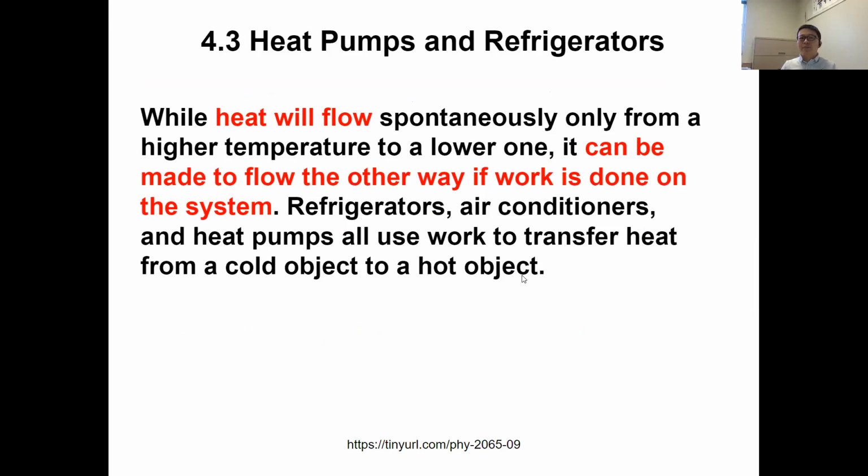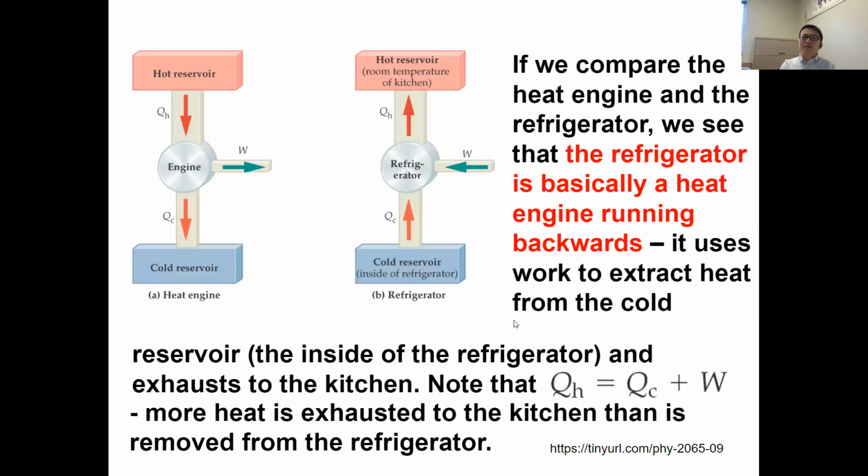Now the heat pumps and refrigerators, so this is the other way around, where heat actually flows from the cold reservoir to the hot reservoir. But in this case, you need to do additional work, okay? So the work is being done on the heat pumps or refrigerators. So it's the reverse of how the energy flows compared to the heat engine. For a refrigerator or heat pump, QC goes in from the cold reservoir through the refrigerator with the additional work W and dumps QH to the hot reservoir. So again, QH equal to QC plus W still stands here.